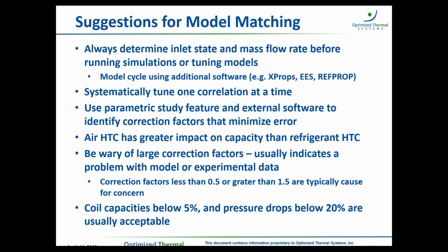The parametric study feature within CoilDesigner can be extremely helpful in determining the right correction factors, especially when we have data sets with multiple test points and we want to minimize error across the entire data set. You can also use other tools like Excel or EES to find the correction factors that will minimize error and help us to tune these models in a more automated fashion.